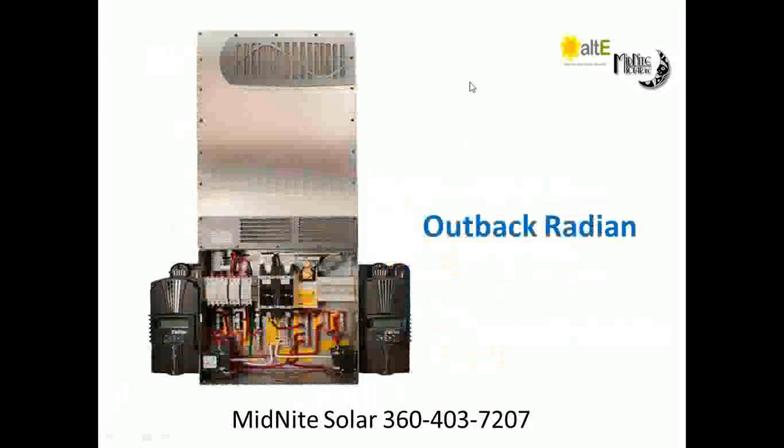Picture of the inside of the Radian E-panel. Again, like I said earlier, fairly similar in concept, a little different in layout. PV positive bus bars over here on the right, AC in, AC out, AC in 1, AC in 2, neutral, PV positive, and then battery negative is up here.